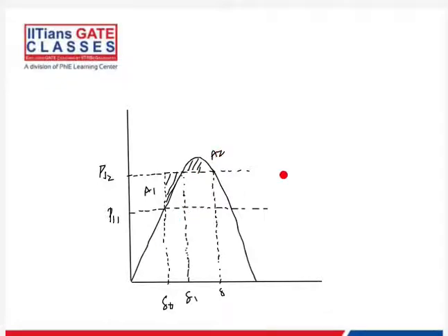In this case A1 will be greater than A2. In order to maintain the stability of the synchronous machine, the actual angle of the rotor during fault should be less than the critical clearing angle. Suppose if this condition happens, then at this point dδ/dt